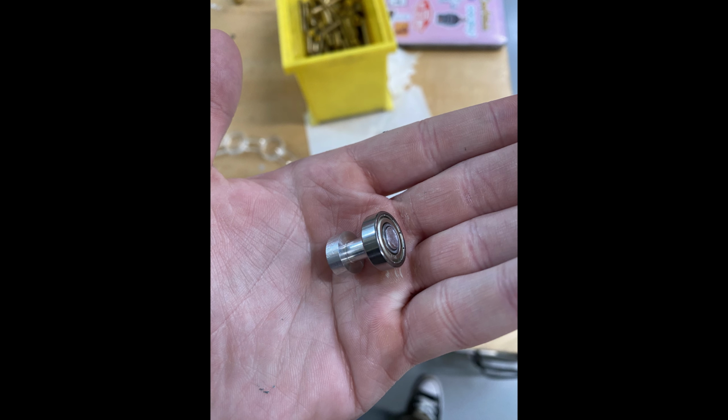In order to connect all of my project components together in an assembly, I needed a crankshaft for the wheel to rotate about. I used a lathe to turn and face a piece of 1/2-inch round aluminum stock. The crankshaft had different diameters on each end because one end was pressed into a bearing, while the other connected directly to the acrylic disc that the plastic shell is attached to.